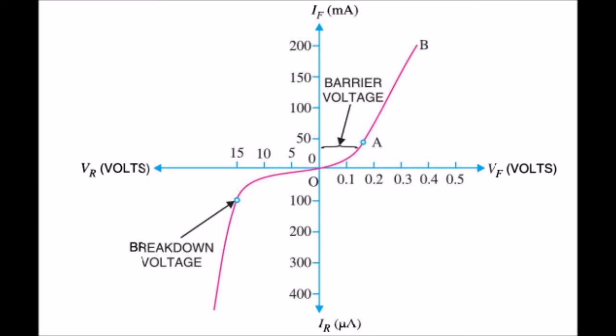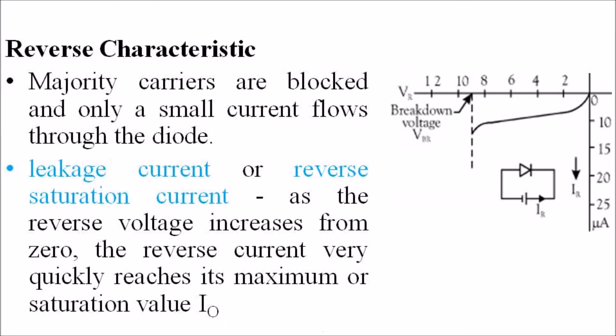As seen in this figure, when reverse voltage exceeds a certain value called breakdown voltage, which is represented as VBR, the leakage current suddenly and sharply increases. The curve indicates zero resistance at this point. So this is represented in this figure with breakdown voltage and the current characteristics.